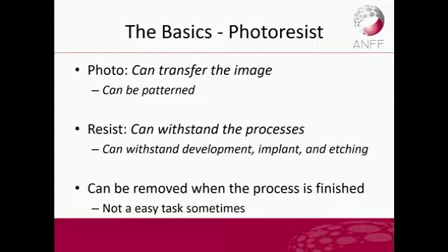Another important property for photoresists is that you also need to be able to remove it when the process is finished. Think of it as a painter's tape. After you paint something, you remove the tape, right? So you don't leave any traces, and it's not going to interfere with your subsequent processes. So removal is actually a very important feature for resist. However, this is not an easy task sometimes. You actually have to use different approaches to remove that polymer layer, especially if they are cross-linked polymers.